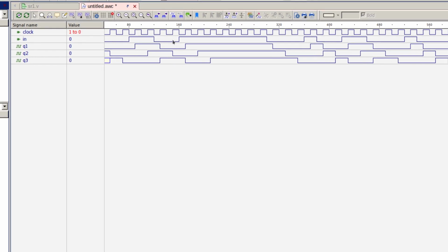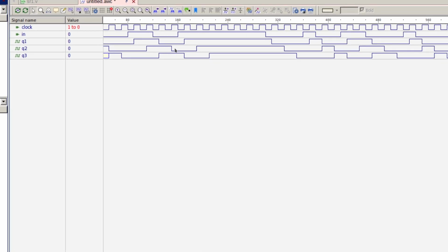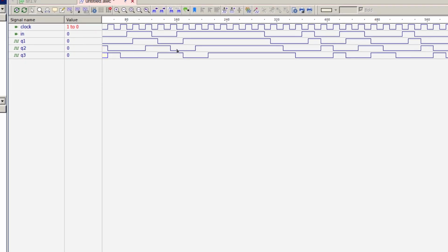And you've seen this before, right? Anybody want to venture where you've encountered this? Kind of in the counter lab we had. Yeah, you saw this in the counter lab. You also saw this in lab 6. This is your delay circuit. Your delay circuit used 2 flip-flops, but the effect is that the output comes out sometime after the input changes. Well, here we've got 3 flip-flops, so we've got a longer effect, but it's exactly the same principle.